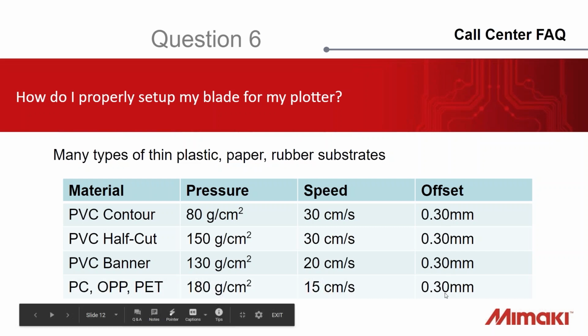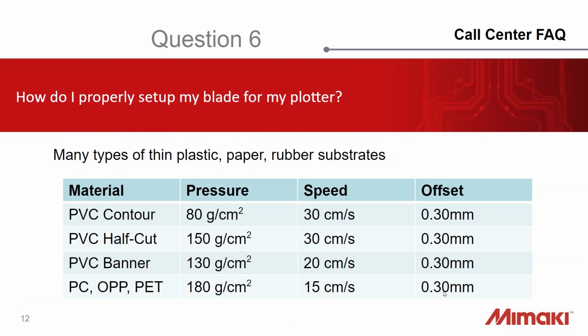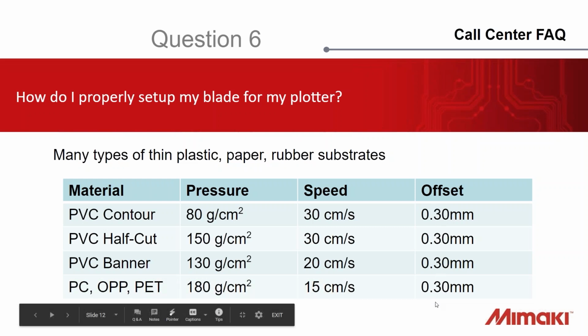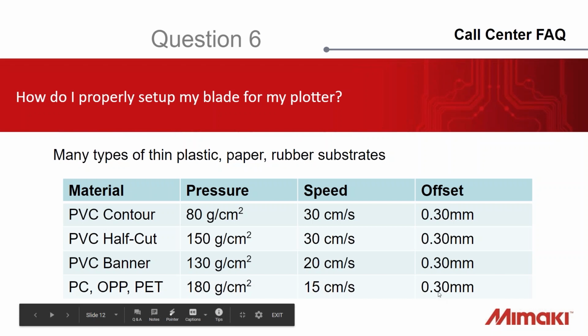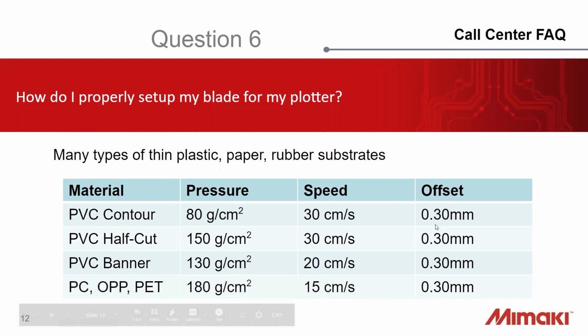So these numbers, if you're, for example, getting blades off eBay or using another blade, since we use an HP pen mount, they're all kind of interchangeable. Generally, if we have an unknown blade, we'll just change these in increments of maybe 1/10 of a millimeter. So I'll try 0.1, 0.2, 0.3, all the way up through 0.9. And then what we're looking for is how well does it corner.